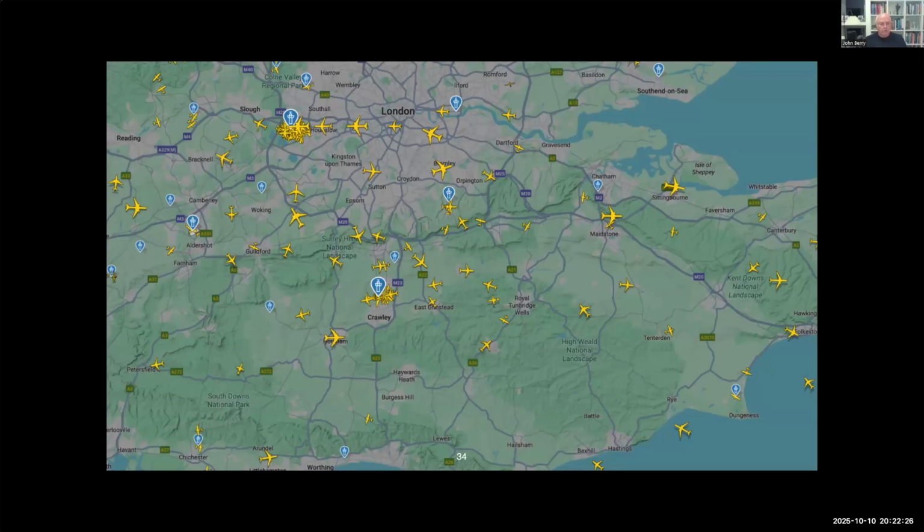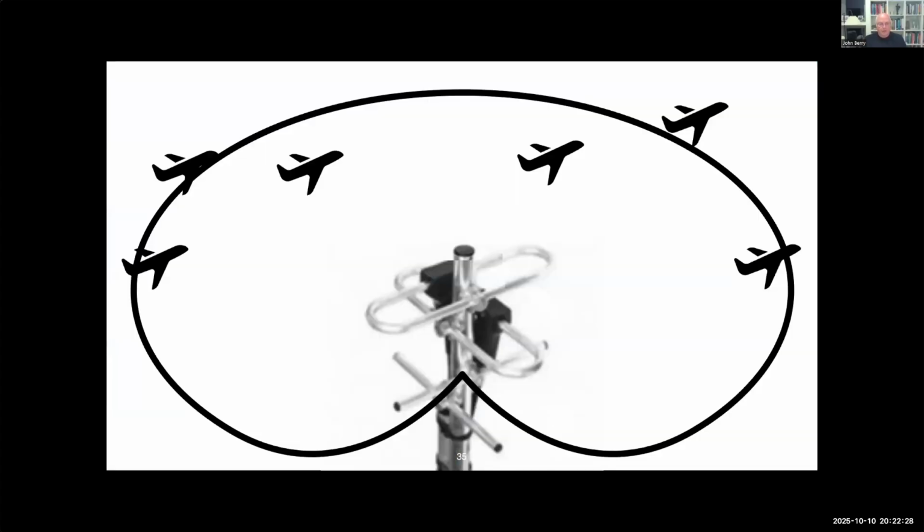And so if you were to use that antenna, now that is what they call a paging antenna, upside down. Typically, a paging antenna, if you've got a big B&Q warehouse and you wish to use pagers or two-way radios, then you have an antenna which basically fires most of the energy down into the warehouse from the outside.